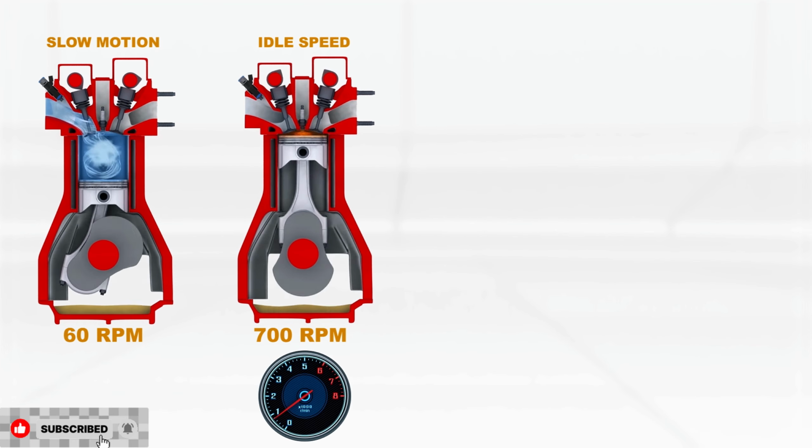The flywheel then stores the energy from the power stroke to use it until the next power stroke. The strokes alternate in different engine cylinders in a certain sequence. This is known as the engine firing order and is required for more stable engine operation.